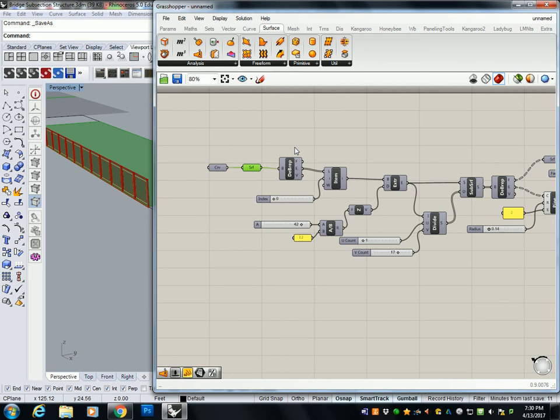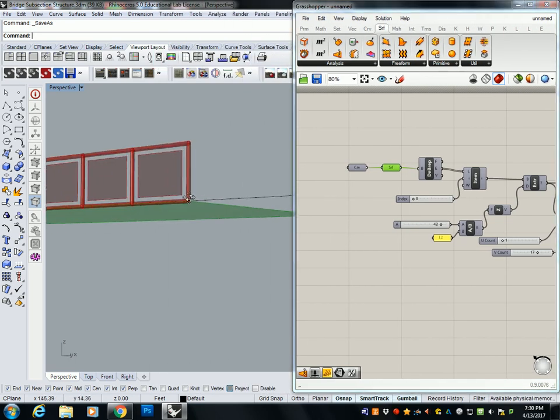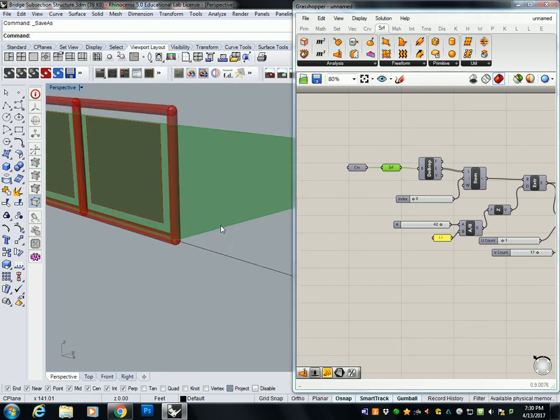And some of you have been practicing this. Not all of you have encountered it yet, but let's say I'm your design critic and I say, this isn't believable. Most guardrails and handrails don't go all the way to the ground. They're lifted a few inches off, and that's for a very good reason: drainage. So water can run off the side of the bridge and won't get trapped on it, because with this one, water would get trapped, right?